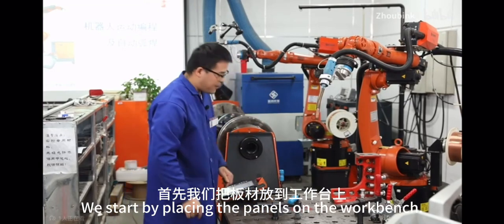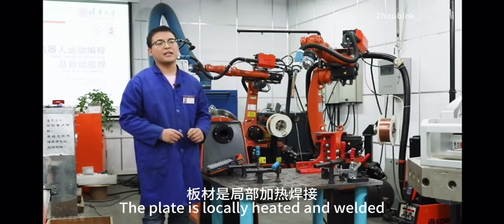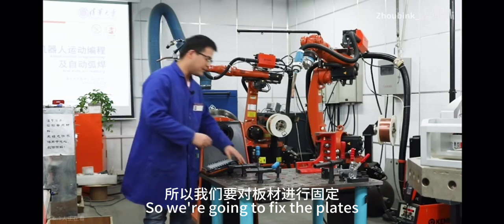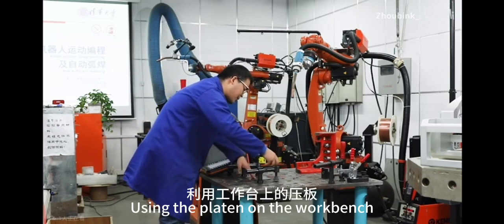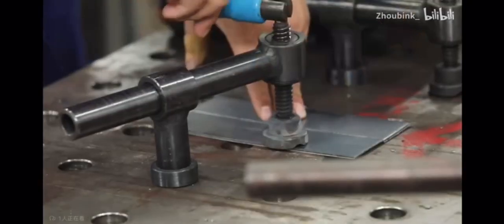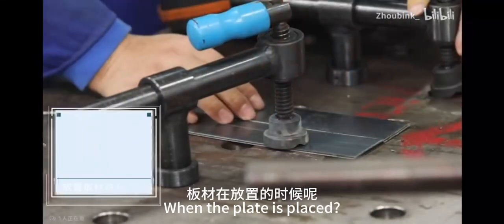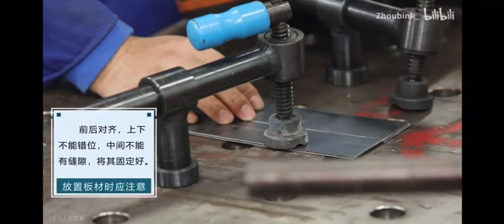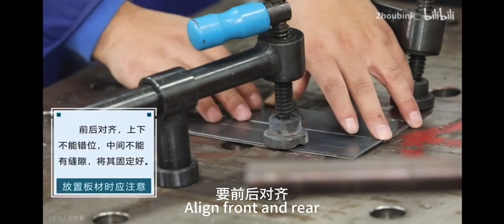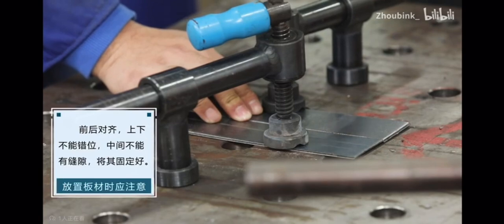We start by placing the plates on the workbench. Because during welding, the plate is locally heated and there will be welding deformation, we are going to fix the plates. Using the platen on the workbench, press the plate onto the workbench. When the plate is placed, also pay attention. Align front and rear. Don't misplace up and down. No gaps in the middle. Fix it up.